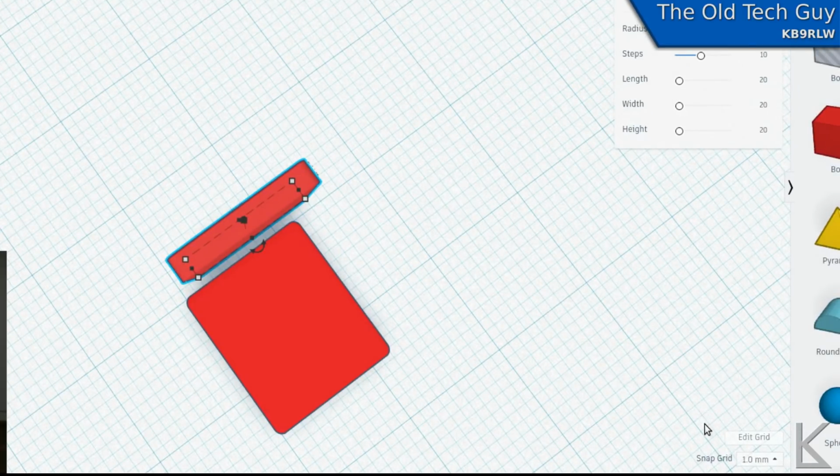And right down here at the bottom edge of the screen is Edit Grid and the steps, and right now it's at 10 millimeters. And you can change that down to as low as 1/10 of a millimeter or as high as 5. And if I hit the arrow keys, that's how far it's going to move the selected shape. So I'll use the arrows to bring that over.